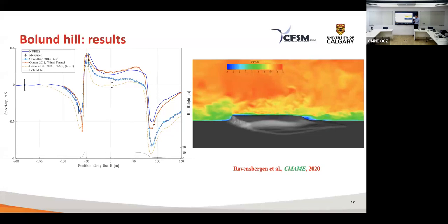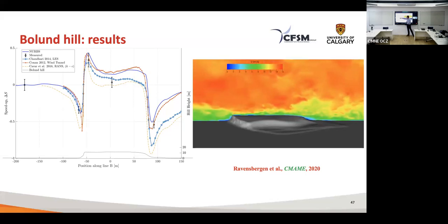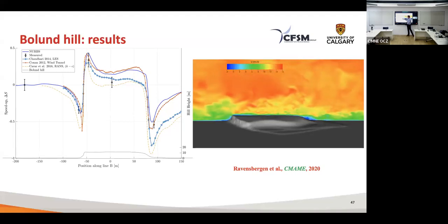If I can, I really prefer to go with a synthetic method, like SEM or RFG, to generate the turbulence. So let's take a look at a few locations. Right at this sharp interface, we are here in blue, and we agree exceptionally well. On the lee side, we are pretty much right within the uncertainty.